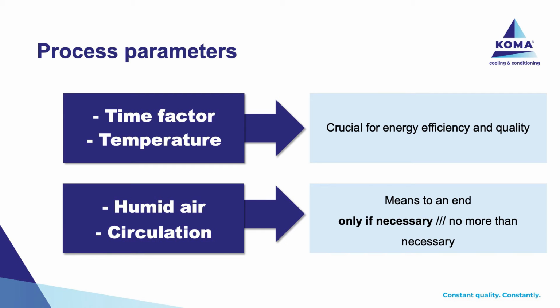In the phase where you start proofing, you add humidity. Important is that your product and your room environment is stable over all phases. So to add humidity is only needed if necessary, demanding from the environment. Important is that at the end of the phase after conditioning, the room should be dry. What we create in this humidity environment is a humidity phase from left to right, bottom to top, front to the back, one stable climate to give all products the same humidity environment.